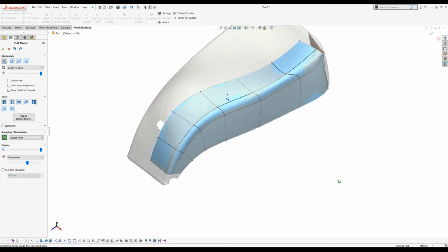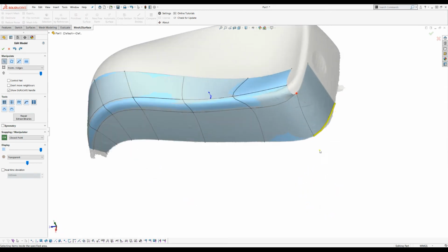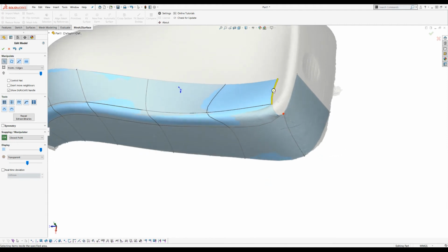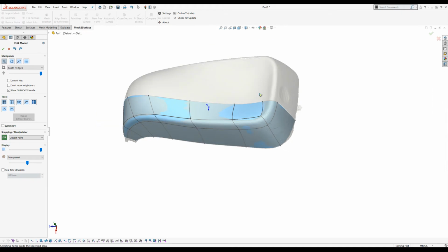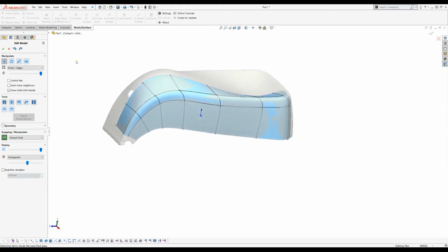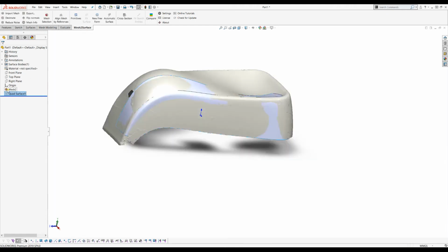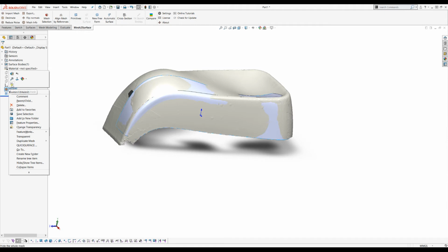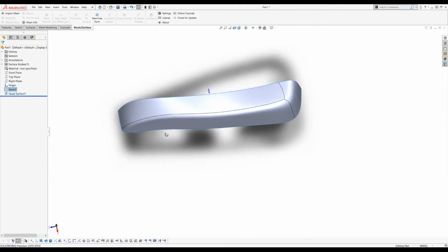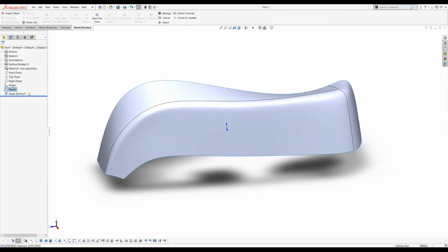So far, this is what we created. It's really nice and smooth, and now I can probably take this one and snap it here, because this looks logical to me. As you see, the software automatically closed this area. Now when I have this surface, when I'm done, I can just press OK, and everything will be created as a SOLIDWORKS entity. Here I will just hide my mesh, and you can see the result of what I have reconstructed so far.